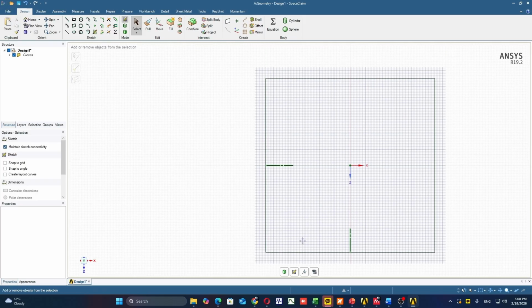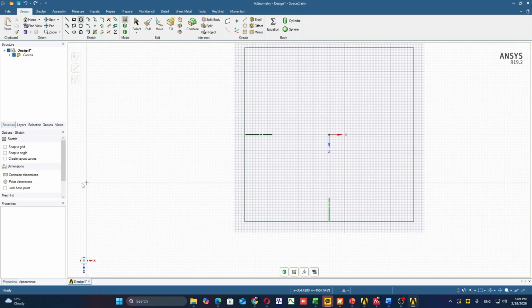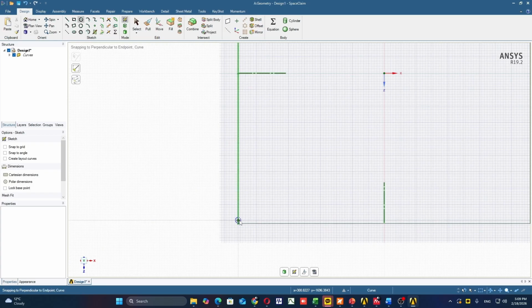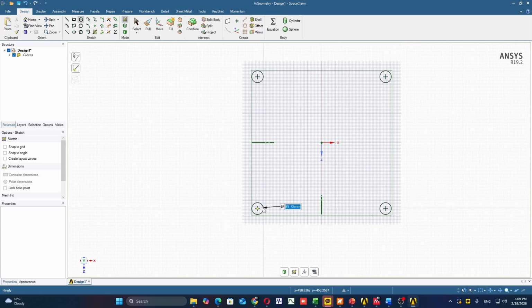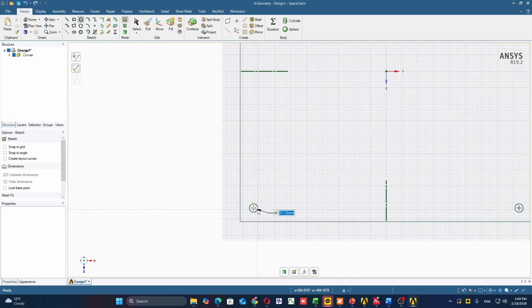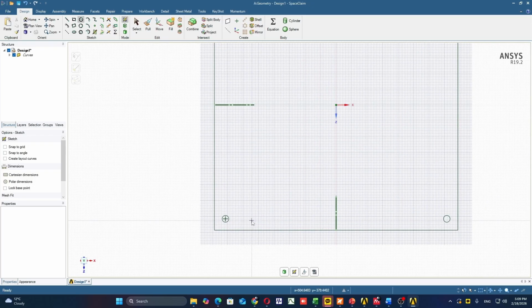Same way, if we do something over here, it will also be mirrored on the opposite axis of this model circle. And use Cartesian dimension first, then put a measurement over here, minus 50 tab 50. So it came over here. See, whatever we draw here, it's actually drawing on the four corners, so it's actually more convenient. And now we put the diameter of 30 mm. It is over here. Done. All four corners are modeled precisely, are drawn precisely.